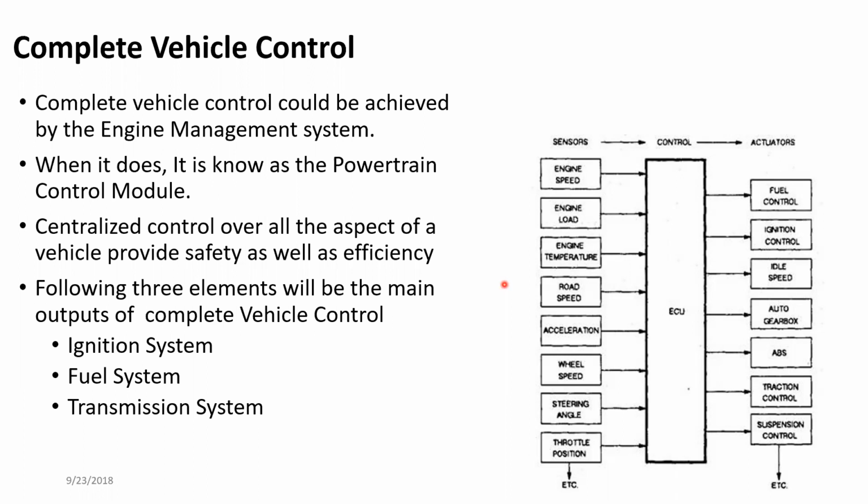The other one is the idle control. As I told you earlier, when the engine is not up to the operating temperature, the engine operates at a higher RPM in order to bring it up to the operating temperature. In addition, when the engine has additional load from the air conditioning system and any other electronic components, in such cases the engine may also need to increase the idle RPM. Those sort of things are done using the idle control, which we discussed in the fuel systems.